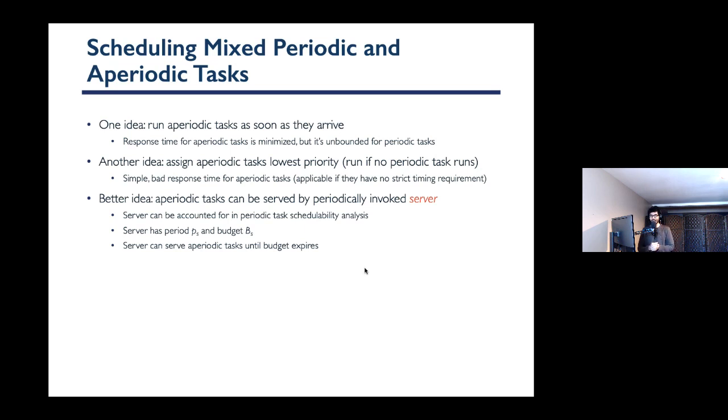We're going to take our aperiodic tasks and tweak them a little bit and make periodic tasks out of them and just introduce them to the scheduler that knows how to deal with periodic tasks, right? So we just convert them somehow in one way or another. It will depend on how we do it.